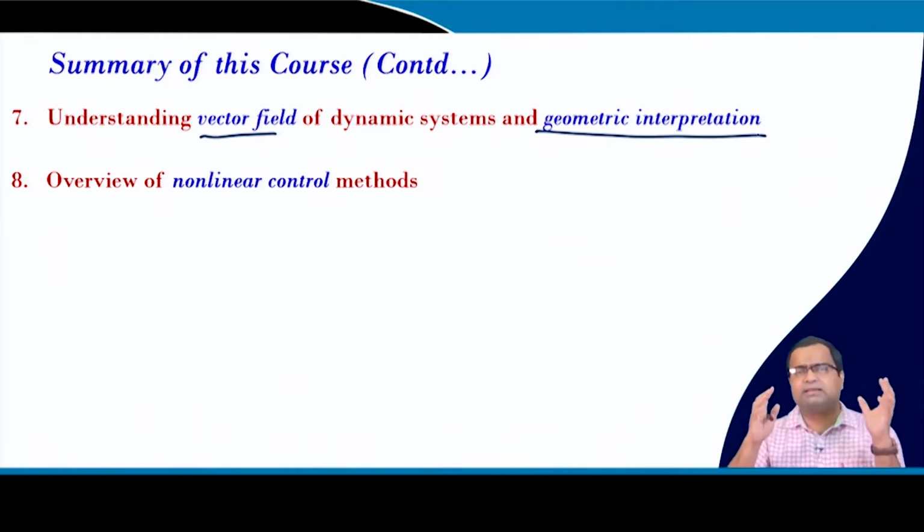And then we have discussed online tuning, a class of gain scheduling technique, which can be used to update the parameters to get a better response. But again these models are derived based on small perturbation, so they do not give enough bandwidth or performance,